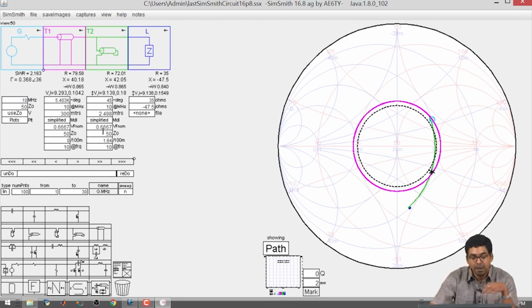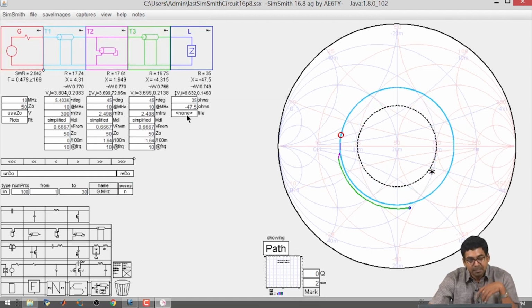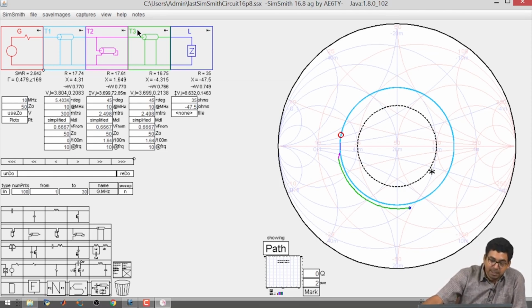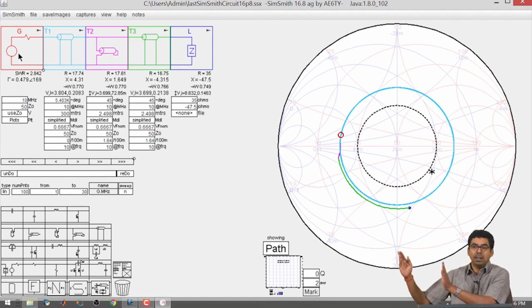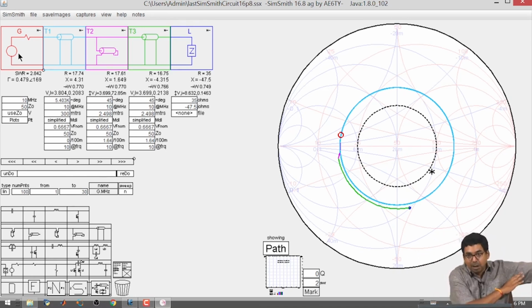That is the advantage. So if I have to control the distance from this, what I will do is I will put another transmission line at the end like this to clearly signify that from the load there is a distance of an ordinary transmission line, and at that distance I have a shorted shunt stub. After that there is a very long cable. So towards the load end I am measuring from the load some distance, standard cable, and then I am having a parallel shunt stub. Okay, and then I am having a very long cable to the left side.